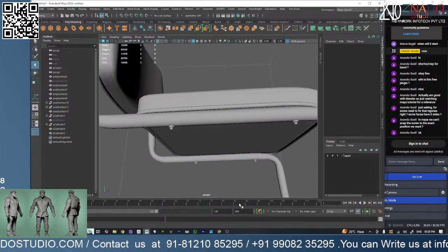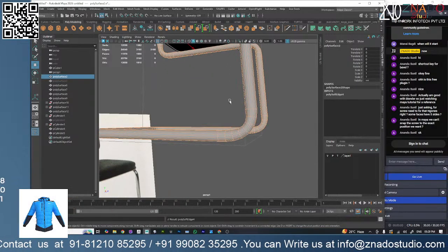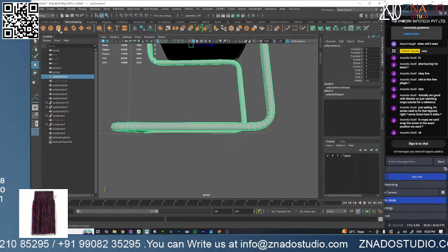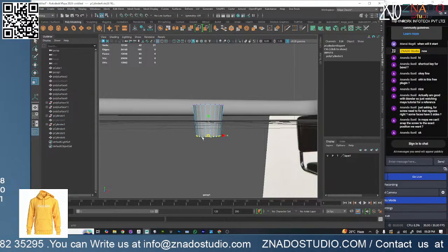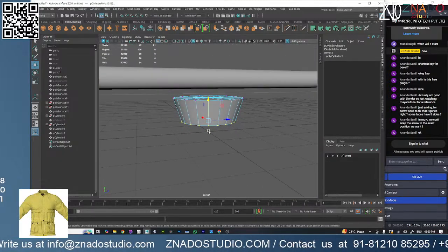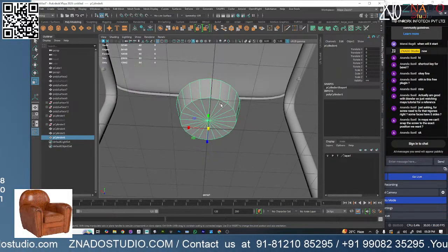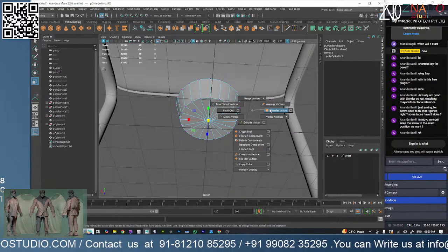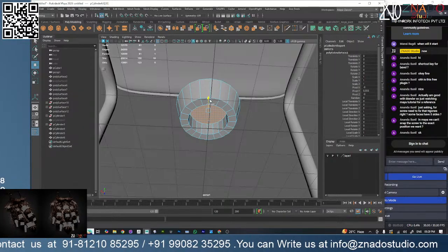So now we have the screws snapped to the bottom, and now we need one more piece, which is the bottom holders. For that, I will take a cylinder, select the bottom, scale it a bit, and push it up like this. These are kind of stoppers. I'll use a chamfer for this, hold space like this, done, and then extrude inside.